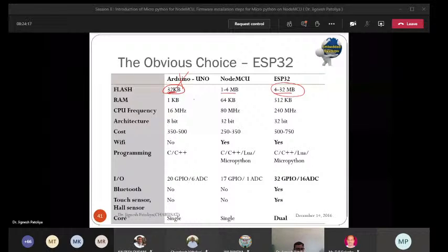If we look at the RAM, RAM is required during runtime. Again, if we want to perform FreeRTOS or RTOS programming in our module, then again it requires huge memory. Similarly, if we want to provide security at a hardware level, again it requires a huge amount of memory, and that is provided by ESP32. Here it is very less. So if we develop some security library in NodeMCU, then it might fail due to the SRAM during running of your code, during execution time.